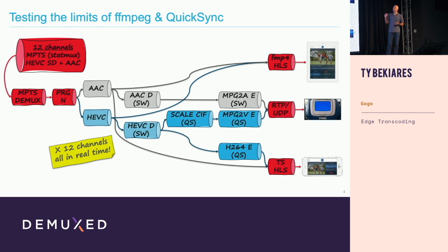The most interesting path, which was very rewarding to actually see work on a real plane, was supporting those old seatback screens. These are seatback screens that were never made to plug into anything other than a DBS IRD. So you would have a DirecTV or a Dish IRD on board the aircraft. It would demodulate the DBS carrier and essentially just dump TS frames into IP packets.